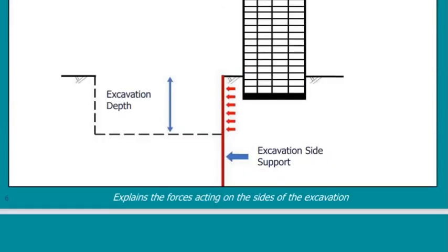Why don't I construct, instead of constructing here a shoring system, why not a retaining wall? The answer is what I've said in the beginning, because to construct the retaining wall, you need a shoring system. You cannot just take the retaining wall and put it in a place. You cannot do this. You need to put a shoring system.